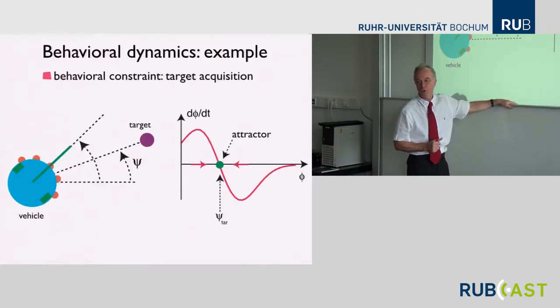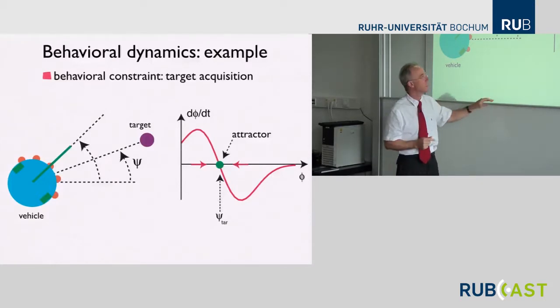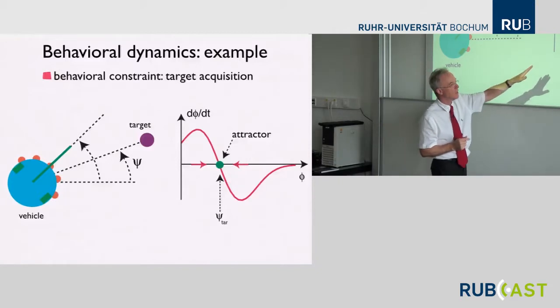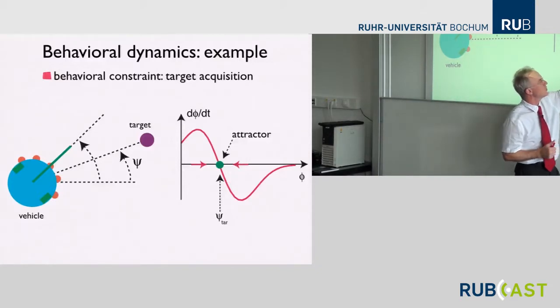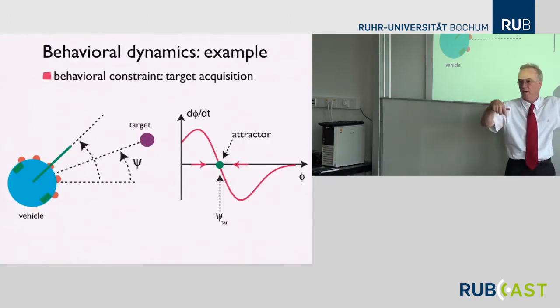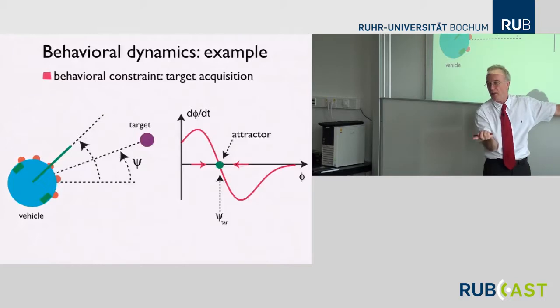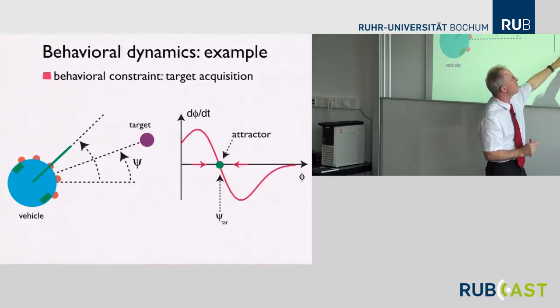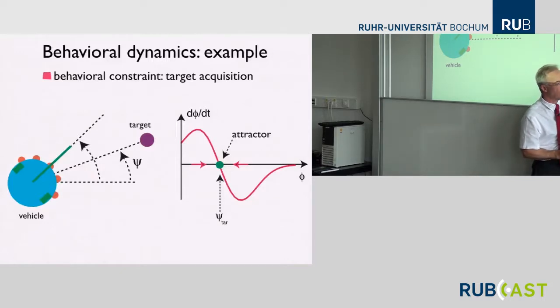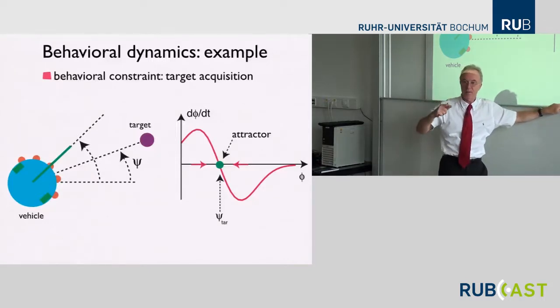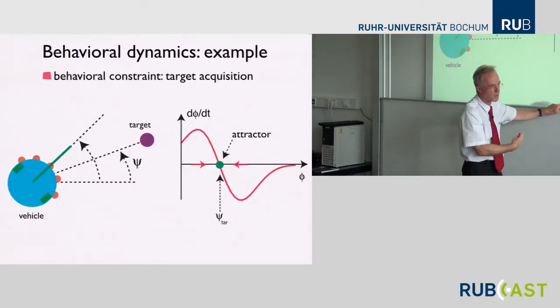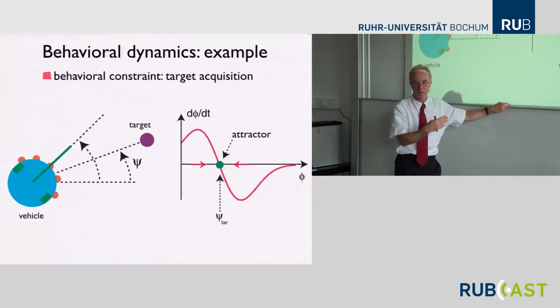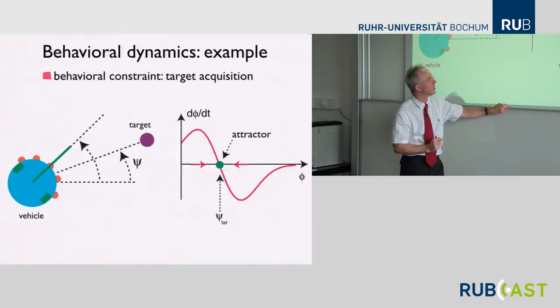If you impose that force, we call that a forcelet, like a wavelet, because we typically limit the range of these forces. For obstacles, we actually, for targets, we don't limit it really formally, but this is an angular variable, right? If you're going through 180 degrees, you're heading away, and then beyond that, you're heading against towards. And what we impose usually is that this is a periodic function, so it goes back to zero and has a repeller on the backside. If not, there would be some jump in the function on the back. So if you were ever to turn away from the target because of obstacles, you would get terrible instabilities when you encounter that jump. So you need to do a sine or cosine function with the right zero crossing for that.